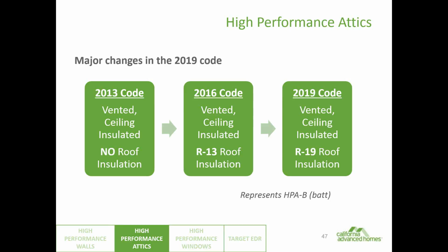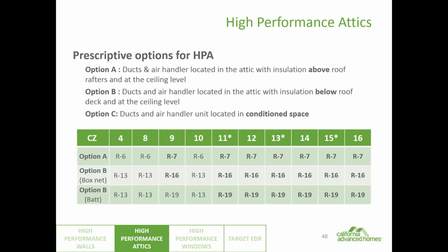So, it's not going away. Let's learn how to build this way, or throw it all out and figure out how to build better so that maybe ducts and conditioned space are real. Maybe that's how we need to be building all of our buildings. Maybe then it becomes cheaper just to do it that way, rather than put them in a vented attic.